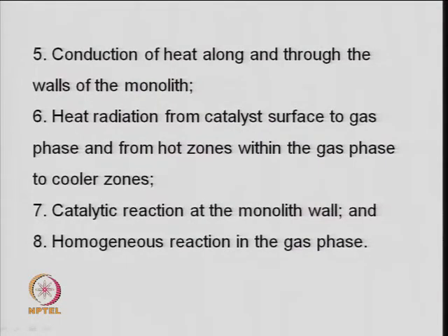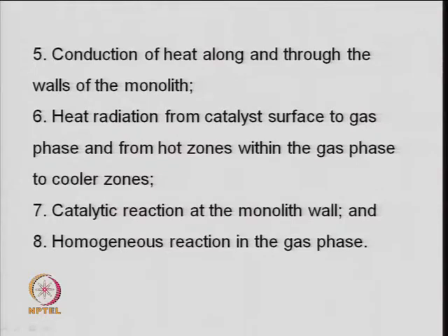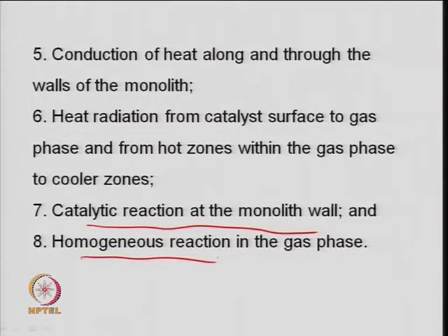Then conduction of heat, because it is a metallic monolith, so there will be heat transfer through conduction also. Then radiation, because of high temperature. Then there is a chemical reaction also, because on the monolith wall you have a catalyst, so there will be a catalytic reaction. There are channels, and lots of void space like the pore space of a catalyst, and in the void space you do not have any catalyst, so there will be a thermal, homogeneous reaction also. You have to look at all these steps when you look at a new kind of monolith design or honeycomb reactor design. So these need to be checked.